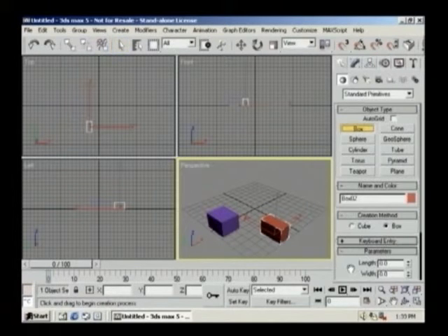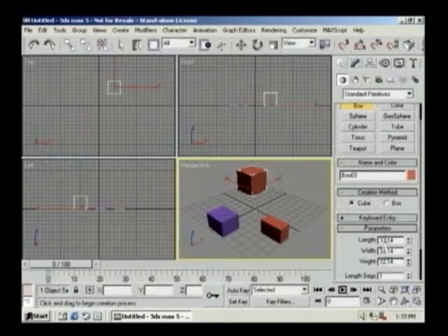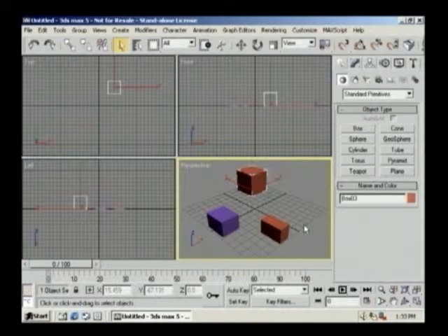And when you're creating a box, you have two creation methods on the Create panel to choose from. There's the Box mode, which we just used, and there's also the Cube mode. If I switch to the Cube mode, and then I click and drag in the viewport, a symmetrical box or cube is created with just one click and drag to determine its size. All dimensions are set to the same. I right-click to end the creation method, and I now receive the previous tool that I had active before I started creating this box.